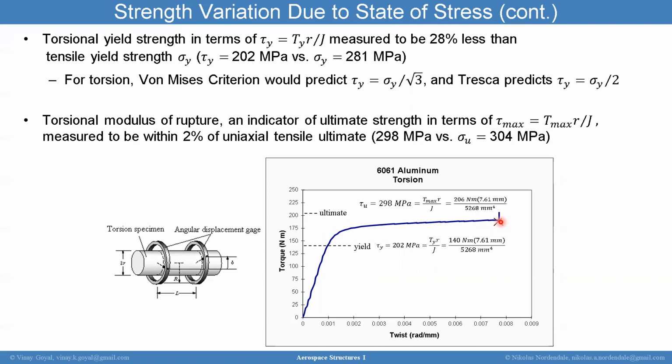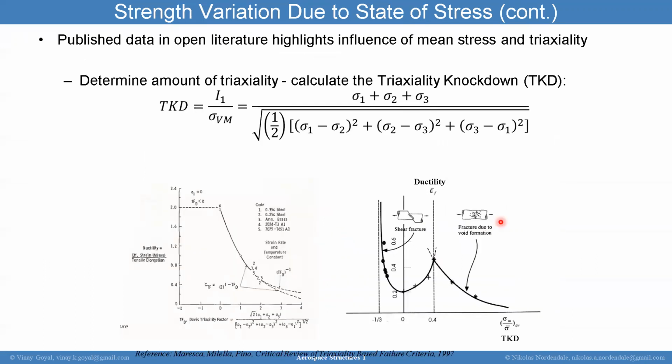Exactly. And that's what we've been hinting at the whole time, which is that stress is a tensor. It's not just one single number, and it's not often acceptable to simplify into a single scalar like von Mises or just look at max principal. It really depends on the loading type. A stress tensor is there to tell you a lot more than just a single number. You have to understand physically what this little block of element is doing. What is its shear? What is its tension and compression? And so that now takes us to the failure criteria we'll be discussing before you go.